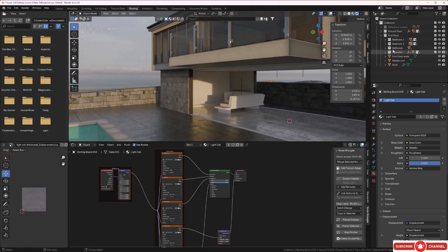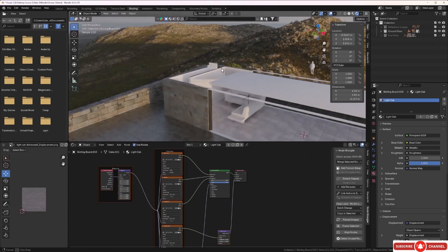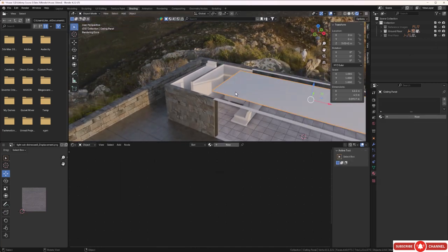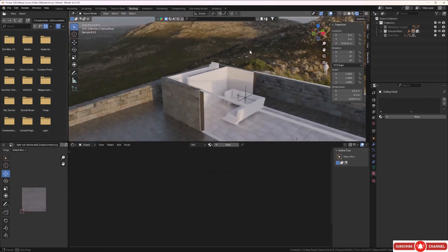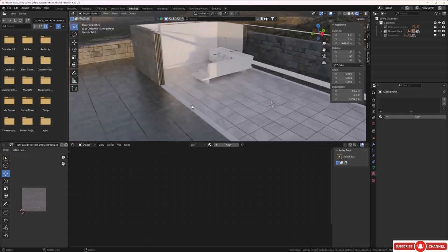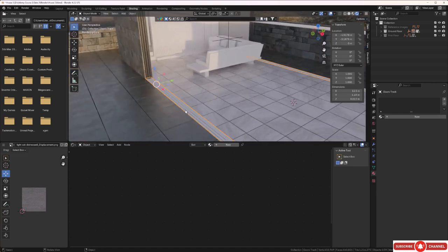So first of all, let's hide the first floor. So let's compress the first floor file and go ahead and hide that. There we go. And let's select this item now. And I think we'll just hide this individually. So I'll just hit H to take that away like that. And I want to work on this sort of feature wall here. And we might as well apply this sort of metal material to this sort of pocket door track as well. So let's go ahead and do those. Let's work first of all on the pocket door track. So I'll select that. And let's check the scale and it's okay.